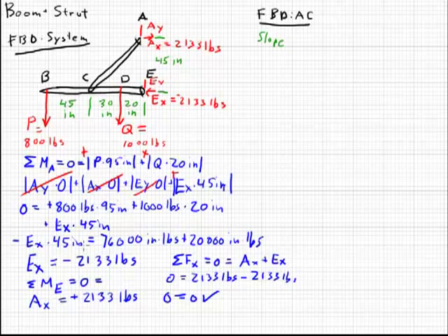So our slope is distance AC in the y direction over distance AC in the x direction, and that will equal the force of AC in the y direction over the force of AC in the x direction. Usually I'll just refer to this as AC in the y, AC in the x. Luckily, this force is also equal to AY and AX.